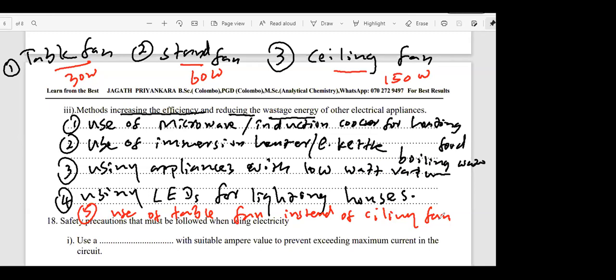If you are putting hot stuff not inside the refrigerator but above the refrigerator, sometimes we are used to putting various objects there, then the energy consumption goes up. Between the refrigerator and the wall, there must be a gap for the better circulation of heated air. If you keep that gap very low, then also the energy consumption goes up. Right? So those things are very important.